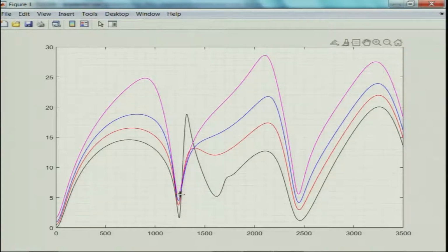For 0.2 it is almost about 5.63 dB, 5.6 dB, and this one was only about 1.5 dB, 1.7 dB or so. So it's basically lifted the troughs, which is more important than the peaks coming down. So in effect the mean flow always tends to lift the trough, and at the same time it tends to lower the peaks. So this effect is known.